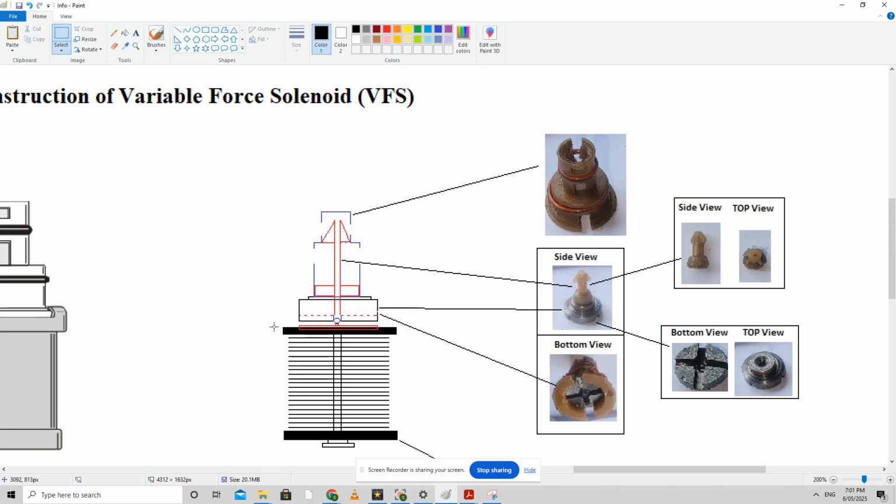When you have this solenoid in your hand, you will see that there is unrestricted access for the fluid or air to go from here and vent out from here. For example, it goes from here, all the way to the bottom through this hole, and then comes out from here and moves right or left. So there are actually four different paths it can take from the vent, but the solenoid itself is marked with only two. Those two are good enough, as you can see. On this one there are only two, one and two. Even these two are blocked, but it does not make any difference.